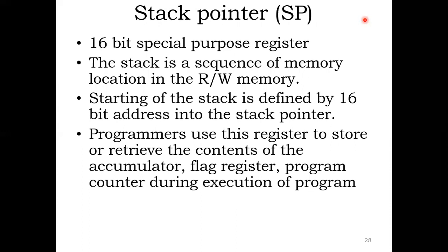The stack pointer is a 16-bit special purpose register. The stack is a sequence of memory locations in the read-write memory. The starting of the stack is defined by the 16-bit address in the stack pointer. Programmers use this register to store or retrieve the content of the accumulator.